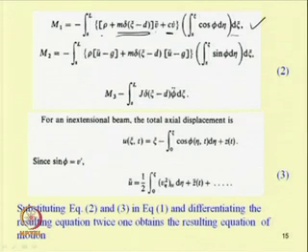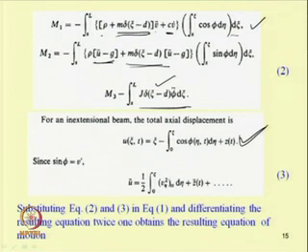Similarly, we can find m2. While finding m2, we have u double dot minus g, along with that, and we should also take this mass into account using this Dirac delta function. And we have this m3 due to that rotary inertia J delta. As we are attaching this mass, we are using this Dirac delta function here, and one can use this inextensibility condition u zeta t equal to zeta minus integral 0 to zeta cos phi.